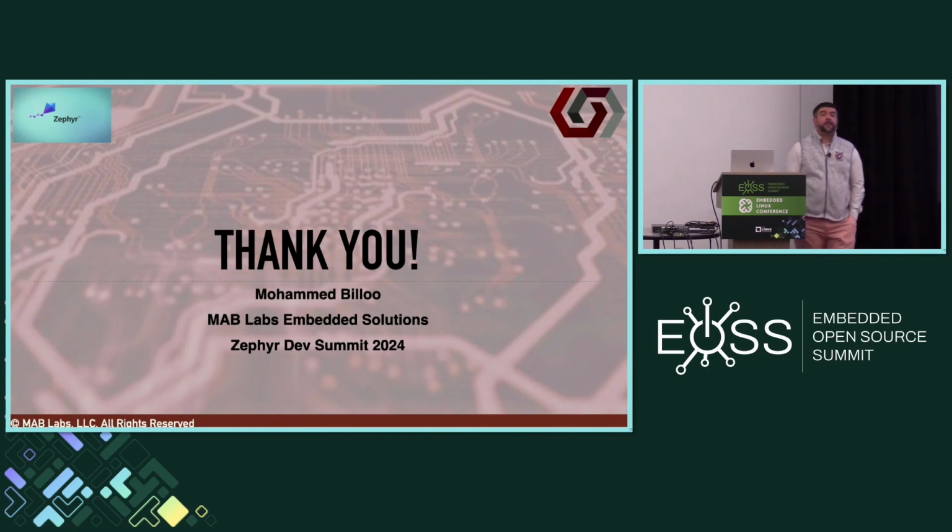I guess you're assuming that the firmware is... where would the Linux firmware and RFS be resident? It would be resident in Flash, right? And then you would have to instruct the Cortex A to... I guess I don't follow. I'm implementing OpenAMP with Zephyr on the i.MX 9.5. So there we can use the boot fuses to launch Zephyr from the QSPI.